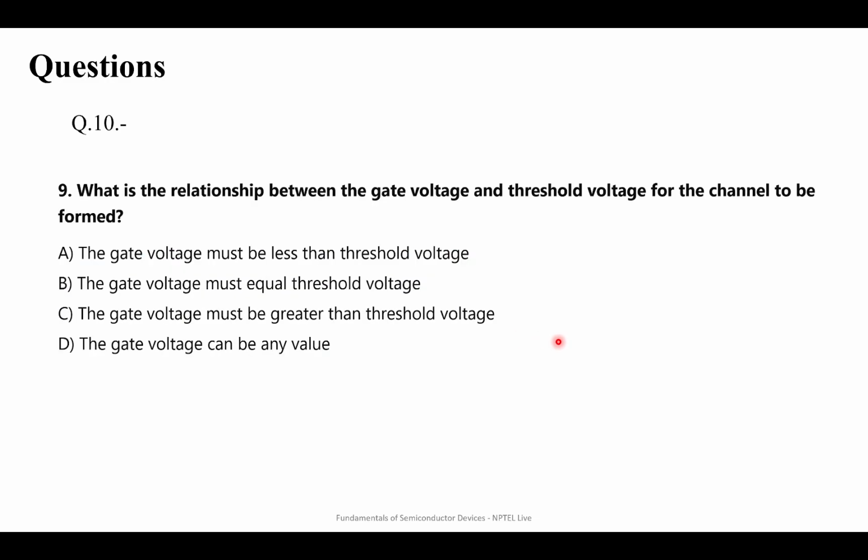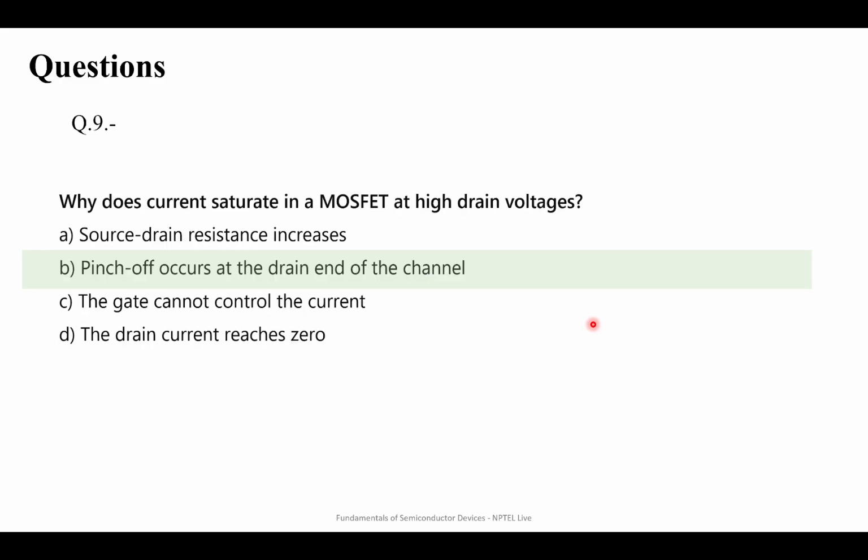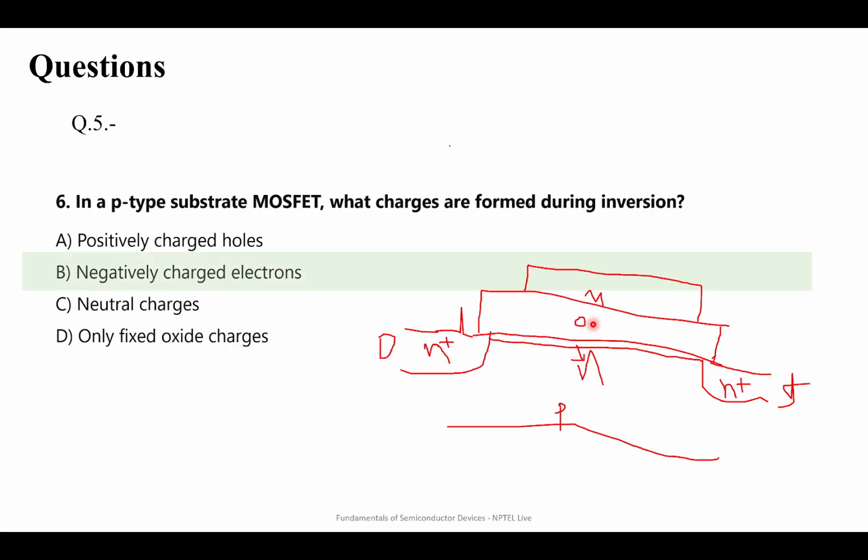Sir, I have just one question regarding that picture. If I increase the drain to source voltage, then sir, the inversion will be more. No, your inversion is coming from your gate voltage. Oh, gate voltage. Okay, okay.